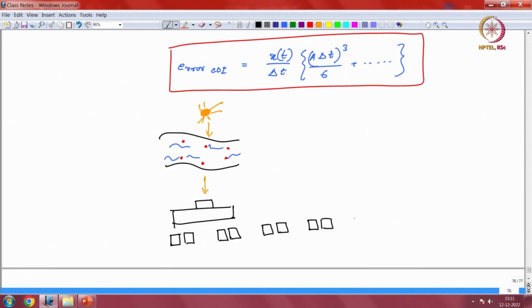So this way you're just going on and taking different image pairs. And when you do the calculation, what you will be doing is you are going to be processing 2 images at once. When you do that, what you end up getting is one velocity field. So maybe this is at time t1, and you get one velocity field for this. Then you calculate the velocity for these 2 image pairs, and then these 2, and so on, right? So now you can see that 2 images here, they yield one velocity field.